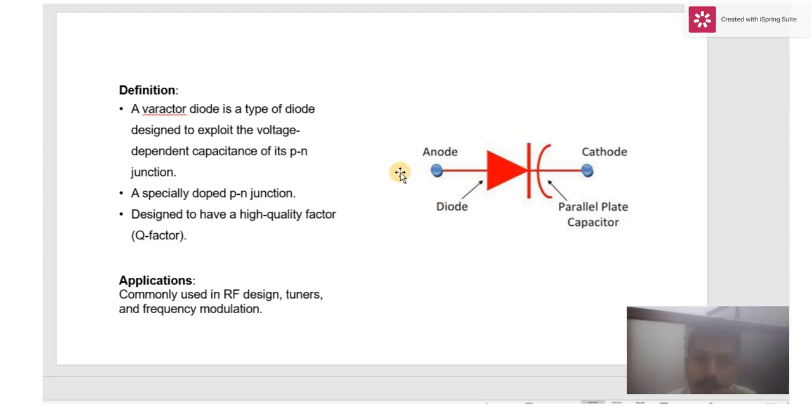One side of the diode represents the anode and the other side represents the cathode. When you apply a positive voltage on the anode and negative on the cathode, it acts as a normal diode. In the case of reverse biasing, you apply positive on the cathode and negative on the anode. In a PN junction diode, normally in reverse bias, it will not conduct. It acts as a high resistance in that region.